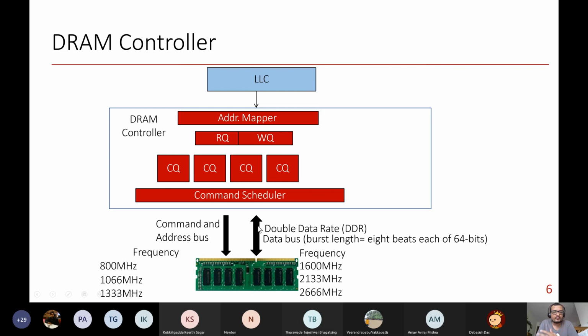After that, you get the response, and this is the data bus. That's why it's bidirectional, right? You can actually write into the DRAM or read from the DRAM. But at a given time, you can actually do one thing. So modern systems don't schedule the writes all the time. Only when this queue becomes full or 75% full, then they schedule all the write back requests, and in that time they change the direction of this bus.